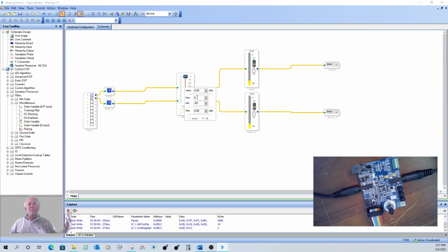We'll talk about this more in another video, but these DSPs, the audio comes in 24-bit, but on this particular one, in the core, it's 28 bits, and it adds 4 bits on the top for headroom. Well, 5, you get the sign bit, but anyways, it gives you more headroom in the DSP. So we actually can get some more gain out of it if you wanted to.